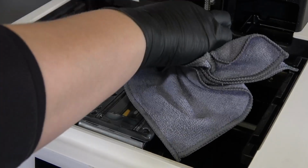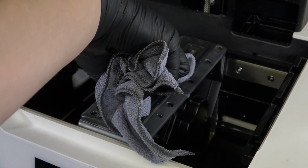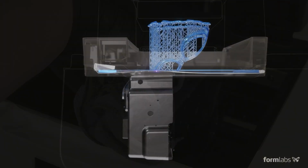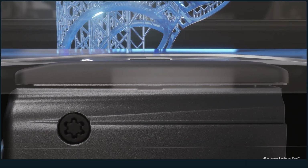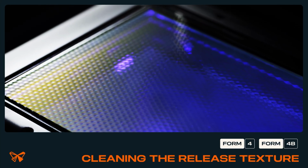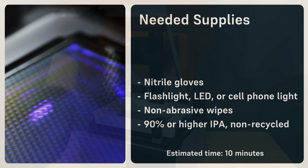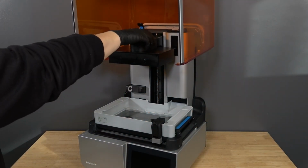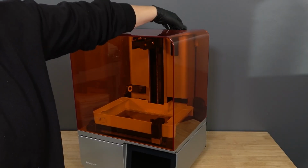If your prints show any of these defects, check your printer's optical surfaces. Those include the optical window on Form 3 and Form 3L generation printers, the release texture on Form 4 and Form 4L generation printers, as well as the bottom of the resin tank itself. If you see any debris or other contamination, clean it off before trying another print. Follow along with our video on how to clean the Form 3 optical window and cleaning the release texture on the Form 4 for further steps.